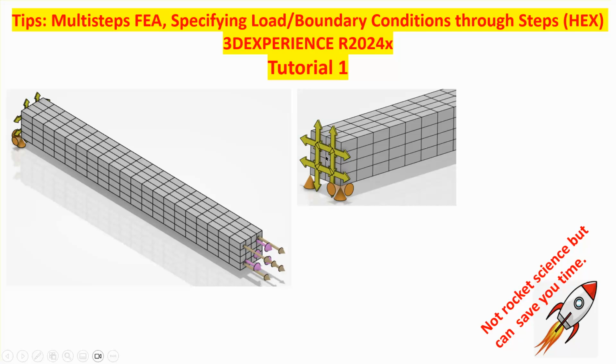So when you think about it, what that means is that essentially this thing uniformly shrinks without having local concentration of stress. If I had clamped this end, I could have done the explanation in that context, but then you would see a very high stress concentration at the clamped area, which I don't want.